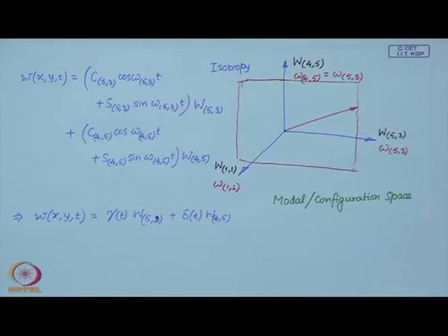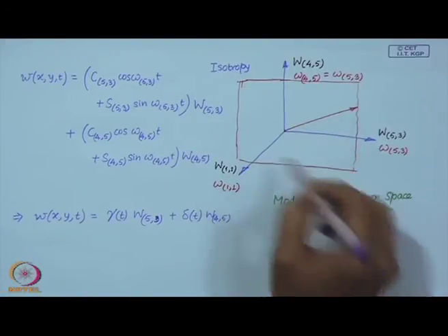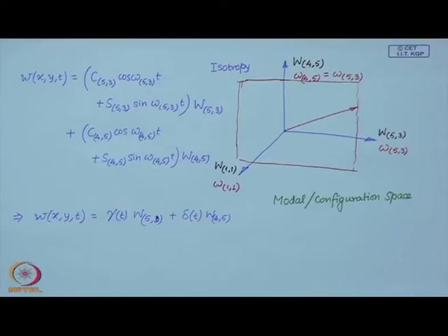the vibrations of the membrane, and it may so appear that the membrane is vibrating in an unsteady manner, because it might be switching from possibly this mode to this mode, or through a combination of these two modes. So, that you can understand from this solution form. So, because of this isotropy of the modal space, we have this kind of a phenomenon.